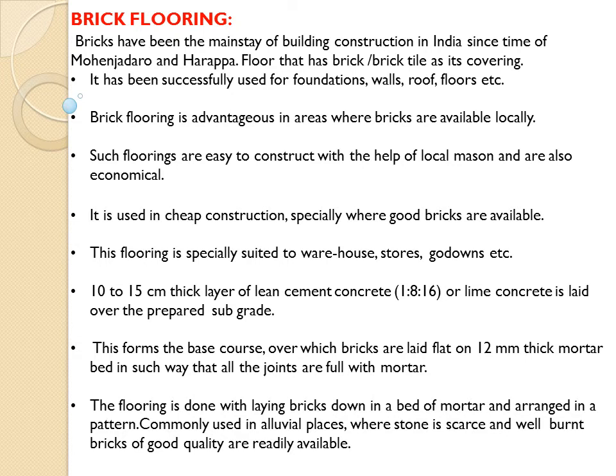So brick is one of the very hard flooring materials, basically used in warehouses because many different kinds of materials and products are dumped in warehouses, stores, godowns. So the movement of trucks, like heavy vehicles, is very feasible. In the same way, 10 to 15 centimeter thick lean cement concrete or lime concrete is laid. So coming to the thickness, the slab thickness is 150 mm, which is nothing but 15 centimeter.